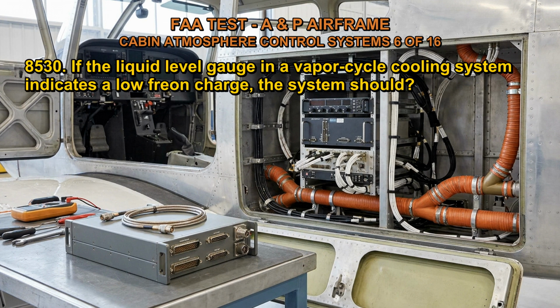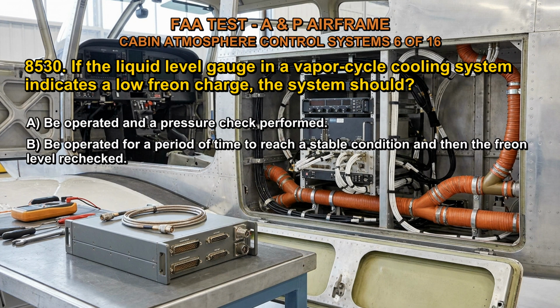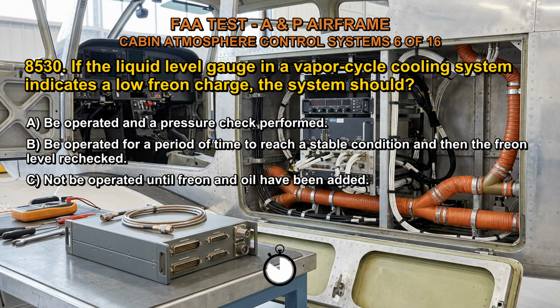8530. If the liquid level gauge in a vapor cycle cooling system indicates a low Freon charge, the system should: A. Be operated and a pressure check performed. B. Be operated for a period of time to reach a stable condition and then the Freon level rechecked. C. Not be operated until Freon and oil have been added. The correct answer is B.